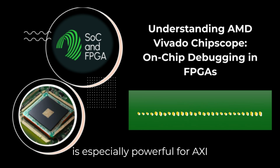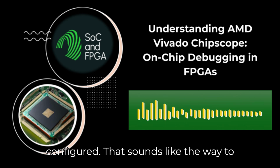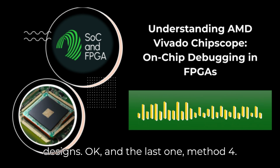This is especially powerful for AXI interfaces. It can automatically instantiate a system ILA for you, all configured. That sounds like the way to go for SoC designs using block diagrams. It's definitely the most natural and efficient method for those kinds of designs. Okay, and the last one, method 4.